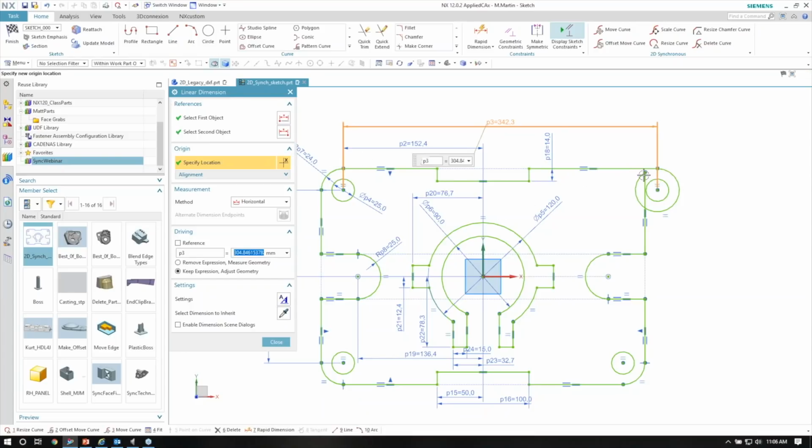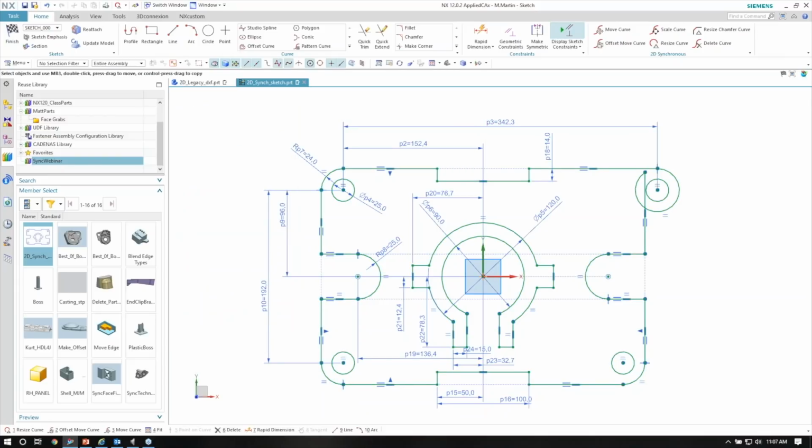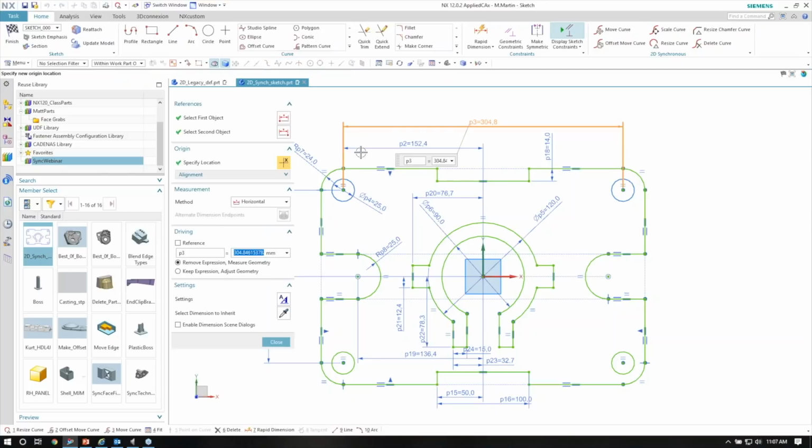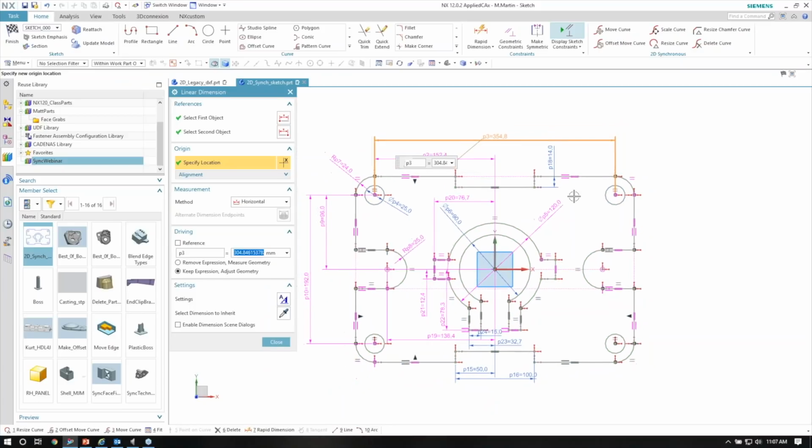I see some things that are not operating properly. Go ahead and close that. I'll Control Z and bring that back. Maybe I can try it a different way. Maybe I just say plus 50, see if I can get it to bump out, and then I get conflicting constraints. And it's just telling me that there's an over constraint condition.